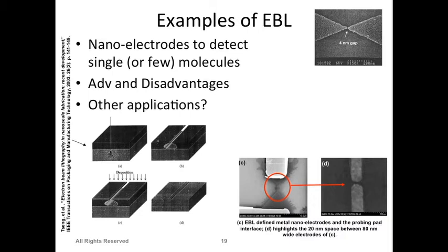And what equipment can we use to really make a small hole? I would go with the E-beam. Electrons normally are not used to drill holes, because they don't provide enough momentum transfer to the materials. But if we use ions, in a few seconds they can quickly drill a hole inside thin membranes, and that's what we did.